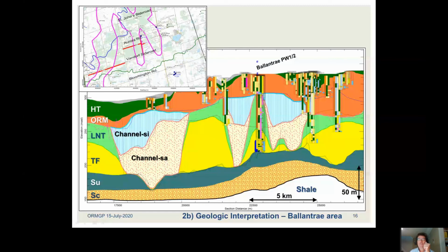We can draw lines of contact, and here we're saying this line is what we think is the contact line between Oak Ridges deposits above, channel sill below. We can constrain where we think we have channels on plan view, okay, so that these lines of interpretation only come into the Kriging when they're within an area that's defined on plan view. So there's a number of different things.